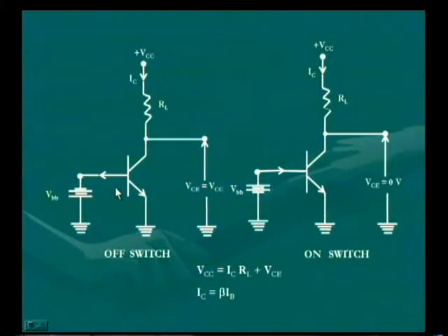If you go for the transistor whose input junction is reverse biased, then in this mode, the transistor will act as off switch. This is because we know that in a transistor, the base current controls the collector current, with the relation IC is equal to beta IB. If you make the input junction, that is emitter to base junction of a transistor reverse biased, then the base current here will be reverse leakage current, which may be 0 for an ideal case. So when base current is 0, automatically the collector current will be 0 according to this equation IC is equal to beta IB.